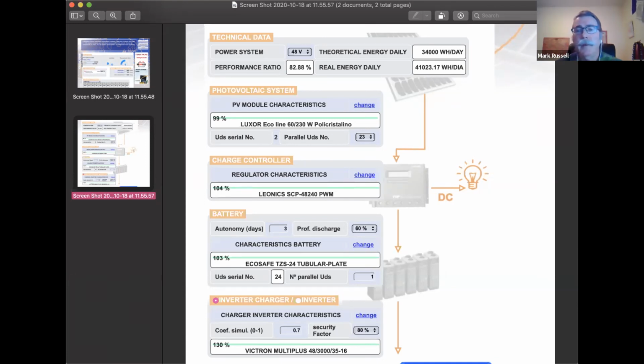It used to be, when a photovoltaic array was $4 per watt, or if you're in a location where you don't get a lot of solar power, it's just not cost effective. You'll run into cases where it's a 30-year payback period on an array that's only good for 20 years.